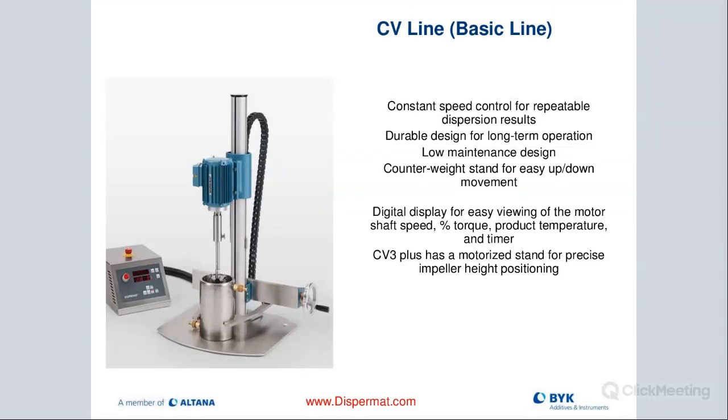We also have the ability to set thresholds for what we call the working area. So we have an upper and a lower threshold that we can set with that slider on this side and one on the back. And that allows us to lock in that working area to ensure that the dissolver will operate in that range. But if somebody were to lift up the machine while it's running, the dissolver would automatically shut off once it crosses that threshold.